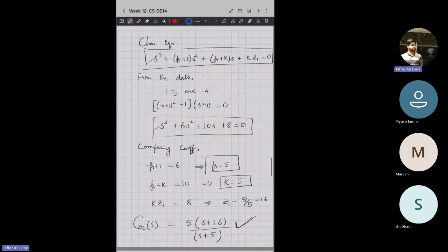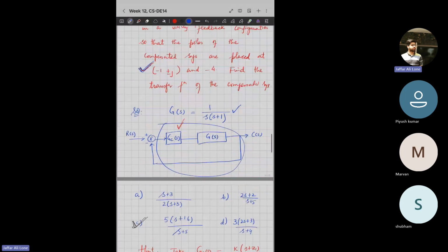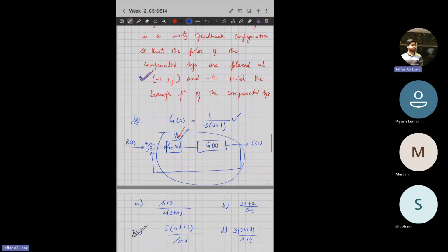you will always connect these compensators in the forward path. So there will be a net change in the transfer function. So basically, what is happening? You are actually either adding a pole to the transfer function or adding a zero to the transfer function. So adding a zero to the transfer function improves its transient characteristics.